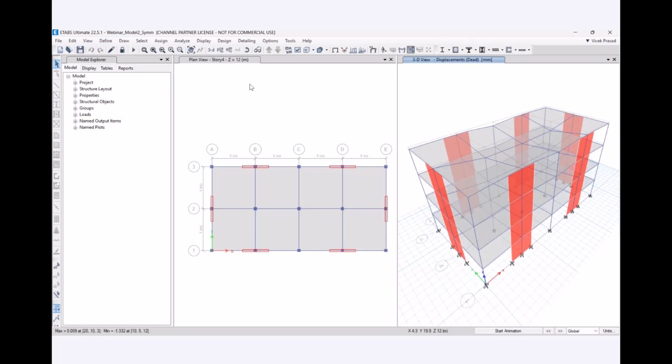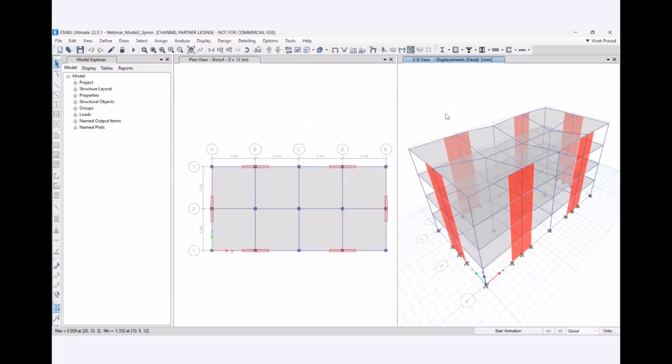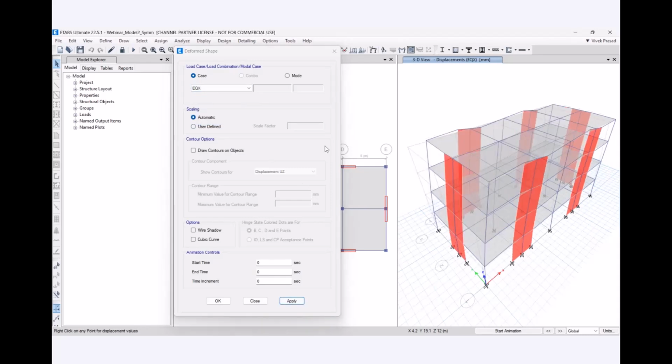Now you'll get to see the deformation specifically. So in the GUI, one of the windows, you can turn it to the displacement. So it's automatically happening after the analysis. You can see this is for the first load case in the list of cases. We'll have to change to the lateral. Start with the static. So we have certain outputs in the GUI, which would be quite useful.